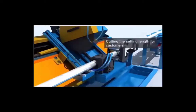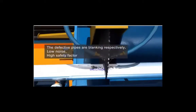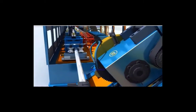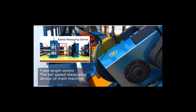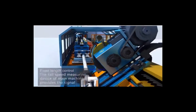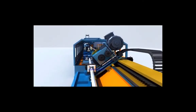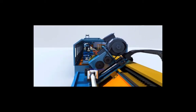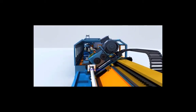The cold cutting saw tracks online and clamps to cut the pipe to the fixed length. It tracks with a servo motor and feeds back the speed to the motion control center with a speed testing device. The motion controller makes a series of actions like acceleration tracking, synchronous motion, hydraulic clamping, cutting feeding, cutting return, car return, etc. Car movement and cutting feeding are controlled by the servo motor.